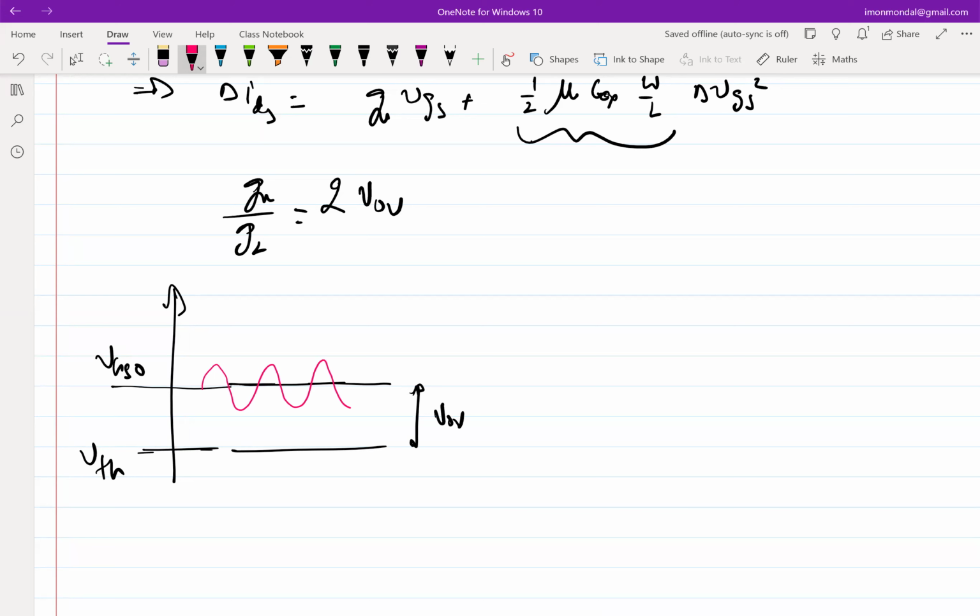So your effective overdrive is changing from this high value to a low value as the signal proceeds in time. Because your device is a nonlinear function of the overdrive, the more of this overdrive you eat out, the more the distortion. So in order to reduce your distortion, all you have to do is reduce the fraction of overdrive that you are eating away.